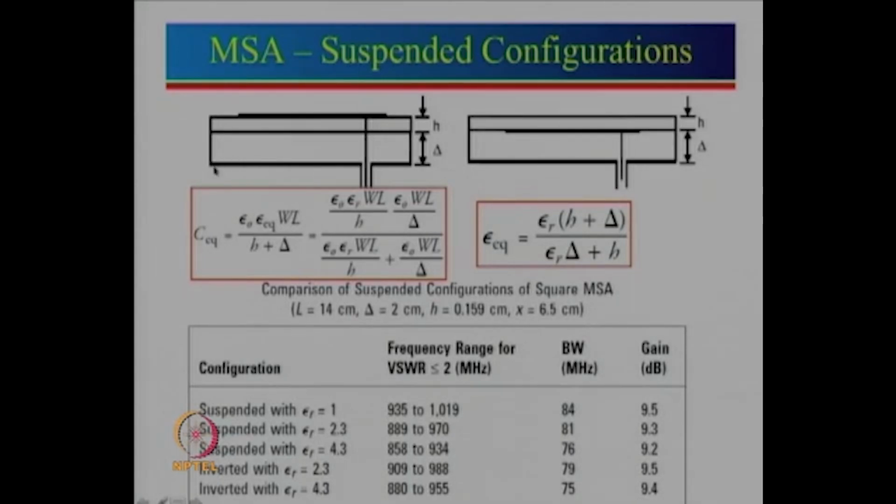And for that metallic plate, again the question is what type of a metallic plate? Well, you can take an aluminum metal plate, or you can take copper or brass, or you can get it gold plated, aluminum plated if you have lot of money to spare, or a very difficult application is required where the tolerances are high as far as the extreme temperature variations and other things are concerned. Maybe you need to reduce the conductor losses.